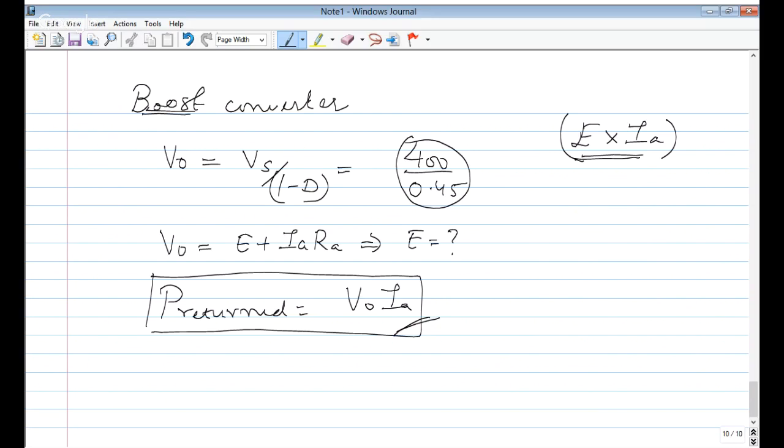Actually, the transformer stampings are annealed in order to increase the core permeability, or in order to give the desirable characteristics to the core. So Rahul, the correct answer should be 4, that is to increase the core permeability.